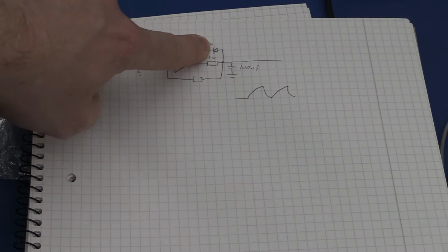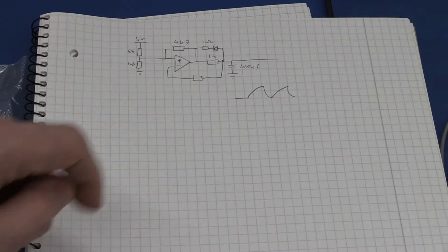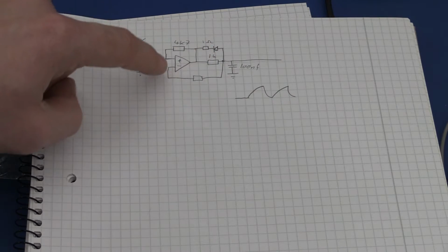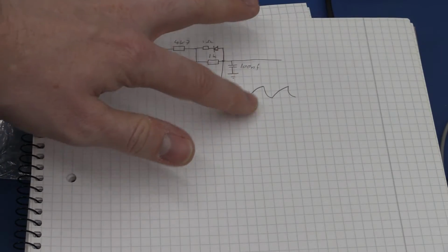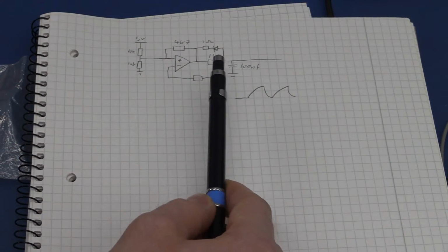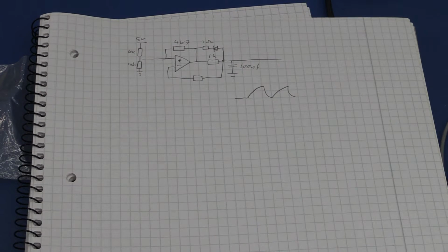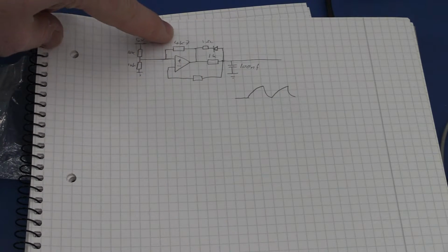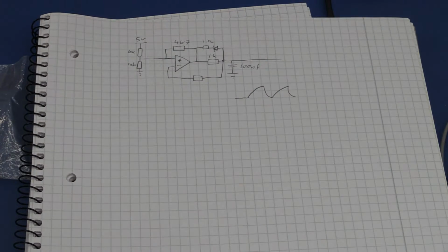You might think this diode will do something to the output, so it's not a completely straight line because it has a voltage drop. But this generator here doesn't go all the way to either rail, and that means we have some wiggle room to allow for the drop of the diode. So actually we will not see it in the output unless you put this division ratio so that the output goes very close to the rails.